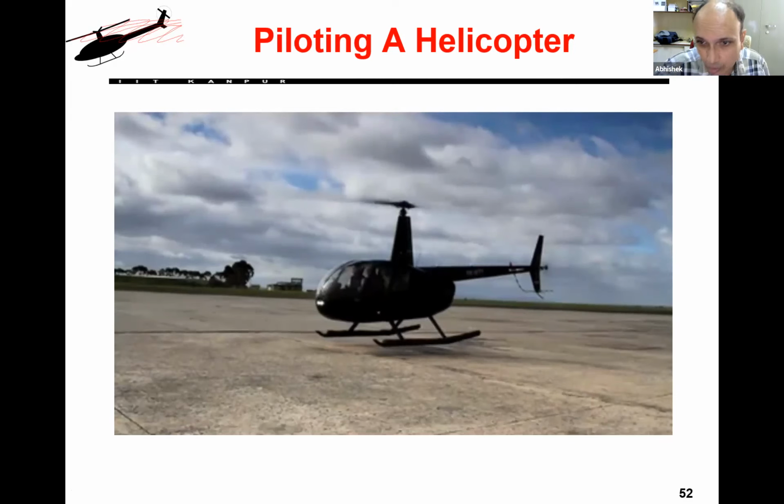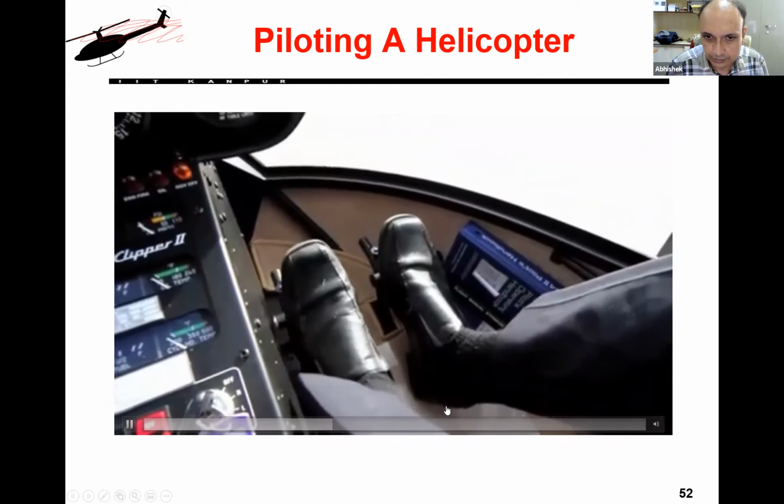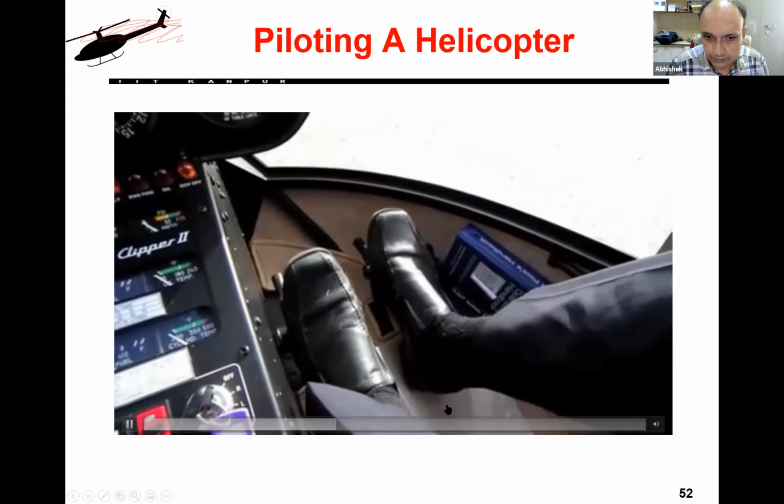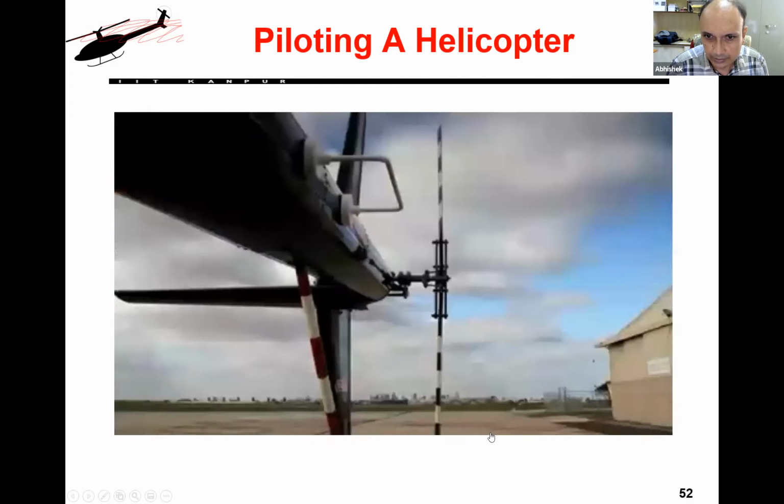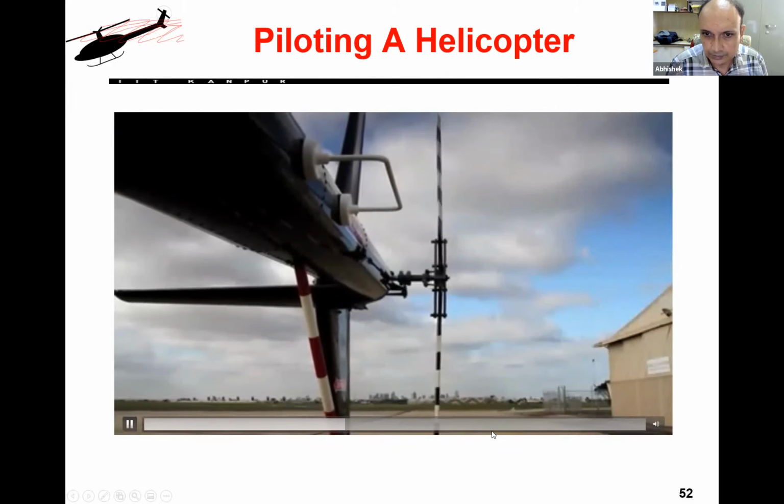At your feet, a pair of pedals manages a similar process at the tail rotor. Pushing the pedals alters the tilt of the tail rotor, which is spinning at a constant ratio with the speed of the top rotor. As you lift off, you need a touch of extra pedal on the right.